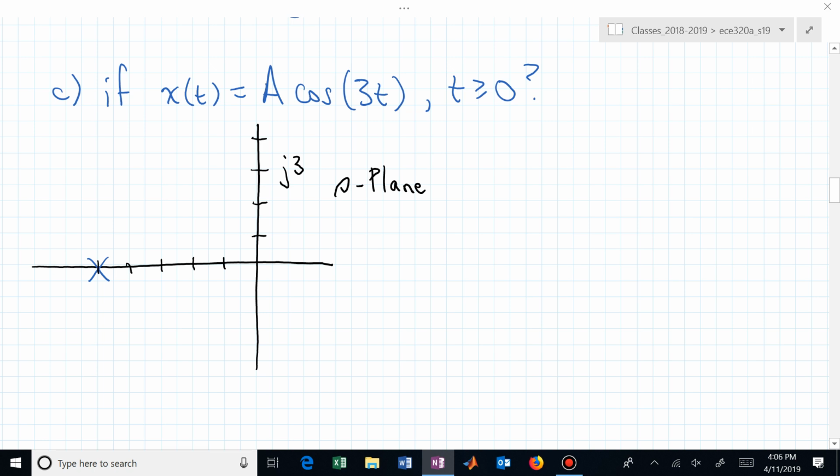And I've kind of given you a hint on this diagram. We looked at DC, didn't we? The origin. Now if we're exciting this system at different frequencies, we're underneath that tent. We're walking on the imaginary axis, and we're going up j omega. If somebody wanted to excite that system with a sinusoid of 1 radian per second, they would walk up to j1 and say, okay, what's going on? What are you contributing from all of the poles and zeros? How many poles do we have? We just have the 1, don't we, in this filter.